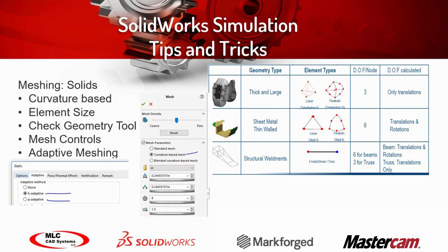So I mentioned at the beginning of our case study the different element types. So we've got the solid elements, sheet metal, which uses the shell elements, and beam elements, which are primarily used when we do weldment profiles, right? The reason why typically you may see fewer elements whenever you've got a sheet metal part using sheet metal features, or weldment beam element profiles in simulation, is because those elements have the rotation elements for each degree of freedom, whereas solid elements only have translation.